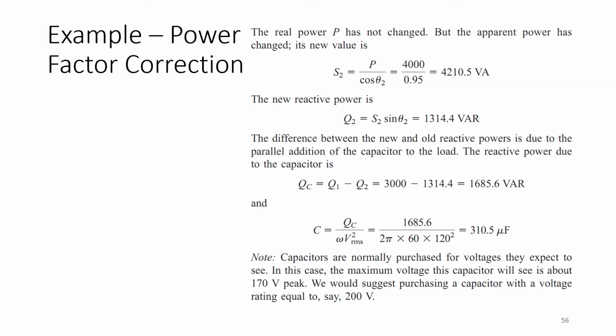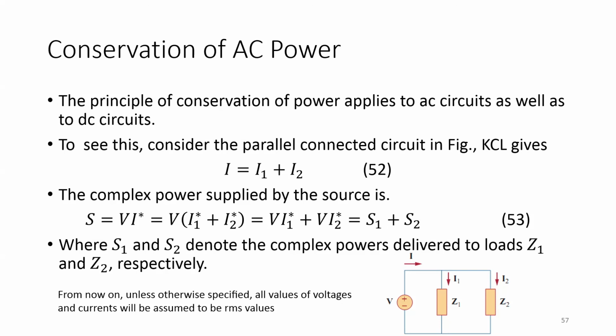So it should be a bit higher than the actual voltage it might face under normal circumstances to avoid any damage under some loaded conditions, heavily loaded conditions. For example, the 170 volt is the peak voltage corresponding to 120 volt RMS. We should consider a bit higher, like 200 volt would suffice in our case.